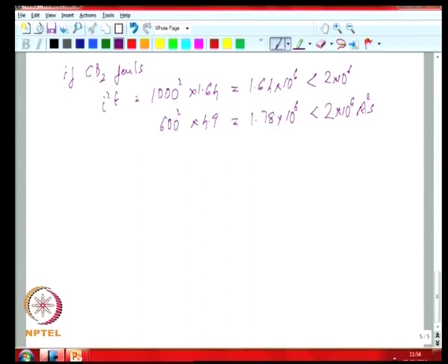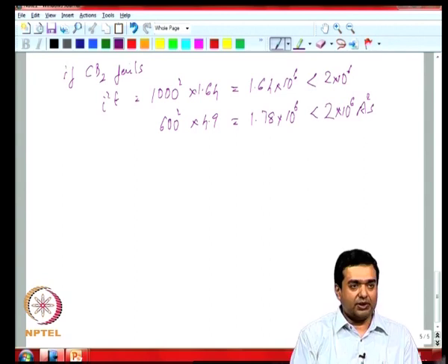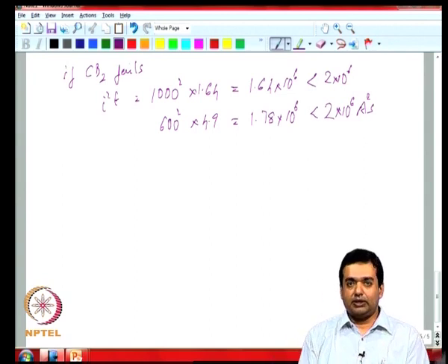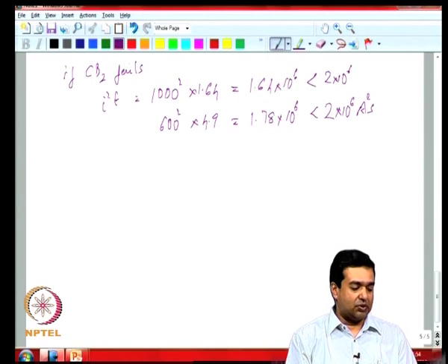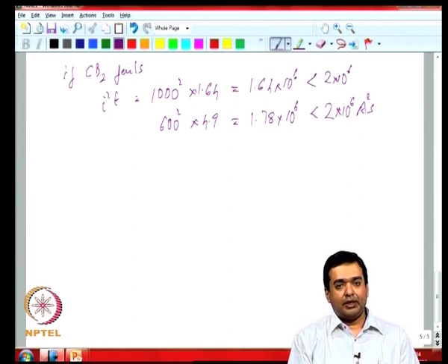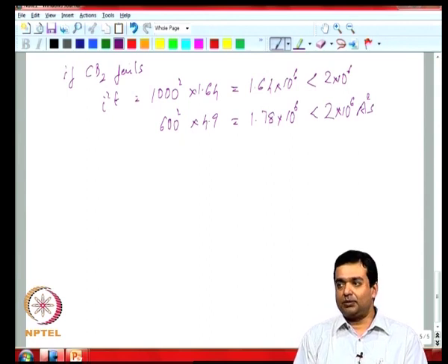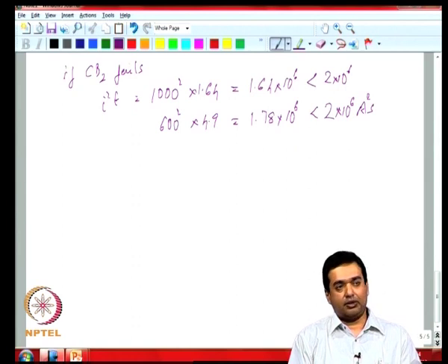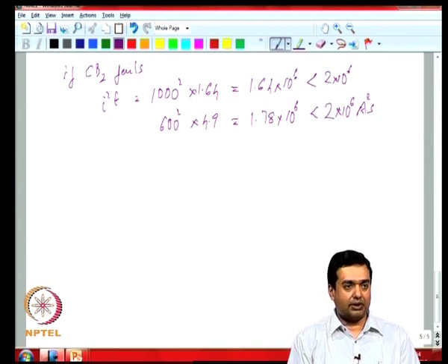So, the next thing that you would have in this particular situation is we had identified 3 zones. So, zone 1, zone 2 and zone 3. What happens for a fault in zone 3? Ideally, we have not indicated what is the protective device that is used in zone 3. It could be a circuit breaker or it could be a fuse. The question is, will the breaker CB2 act as a backup, and if it is acting as a backup, what is the fault I square t that is happening in zone 2.